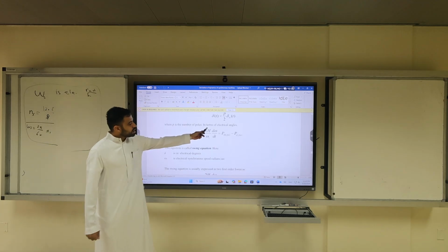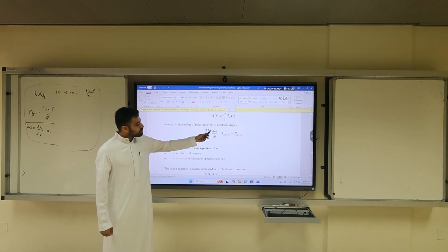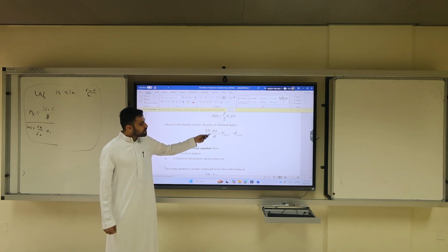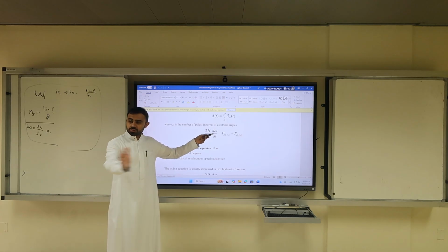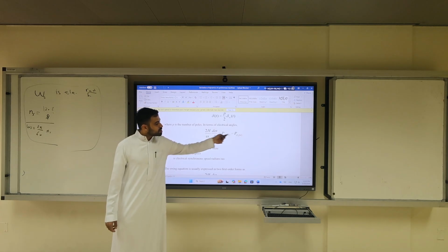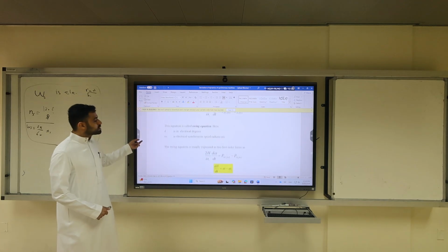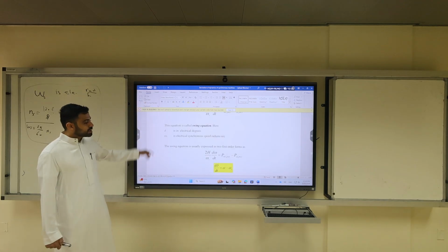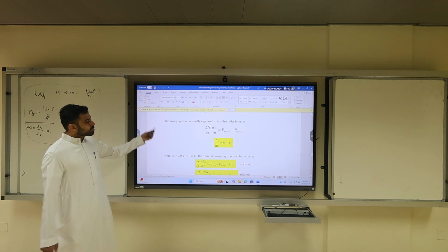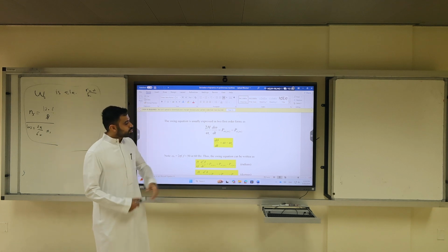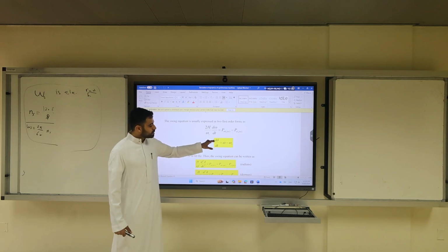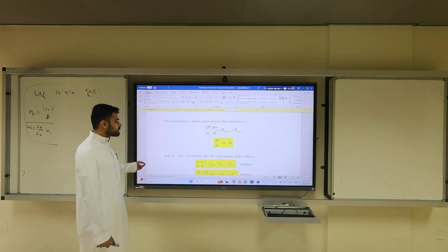2 times H times omega over omega_s times the rate of change of omega. This rate of change is the rate of change of the electrical frequency converted to radians per second. And then you just subtract the powers in per unit. So this is the swing equation where everything is electrical. The swing equation is usually expressed in 2 first order forms. So d delta over dt is omega minus omega_s.